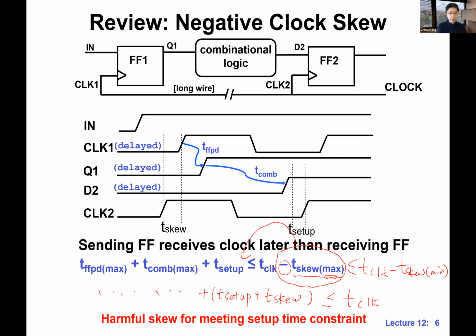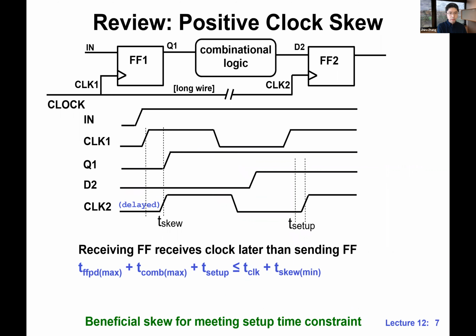If not, let's move on. Let's look at the positive skew. Most of you, I think, agree that this is good. This is good for meeting the setup time, and good for minimizing the clock period. Here it's called positive because we have a plus here. This is a plus. That's why it's called positive.